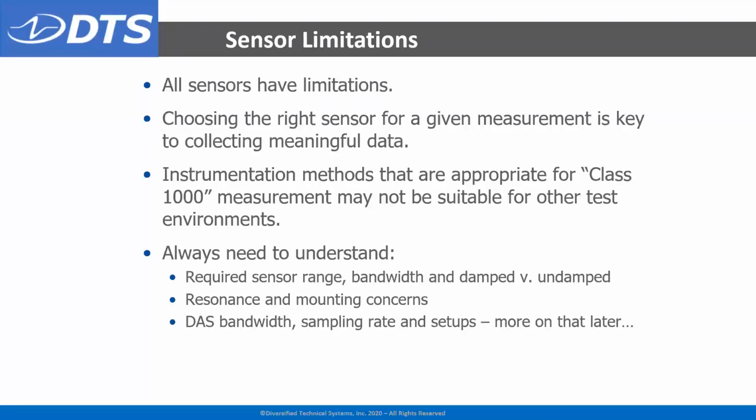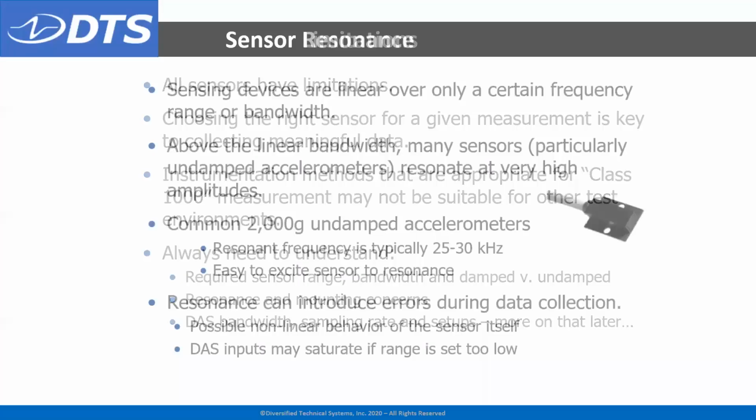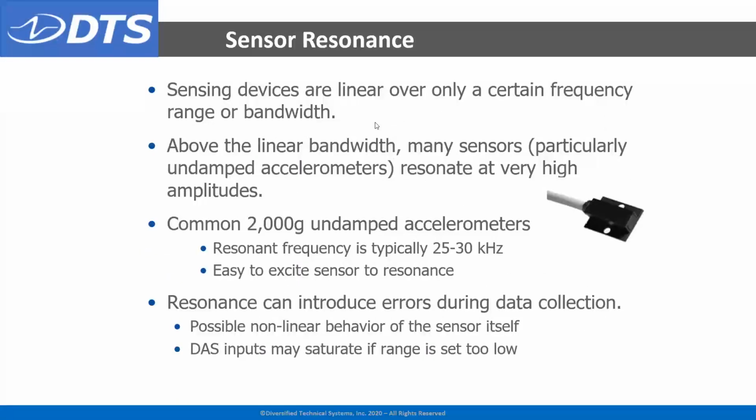Resonance and mounting concerns are huge, and we're just going to touch on the surface today, but I'm going to point you to some other information. And then, of course, you're recording all the signals with a DAC or data acquisition system. You need to think about the bandwidth, sampling rate, and setups. So let's get into this topic of sensor resonance a bit here.